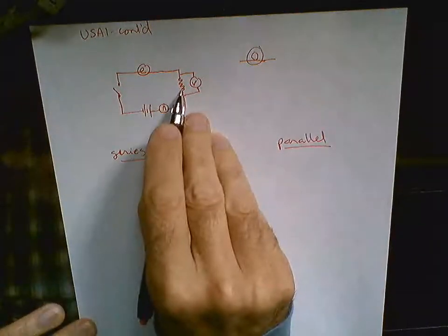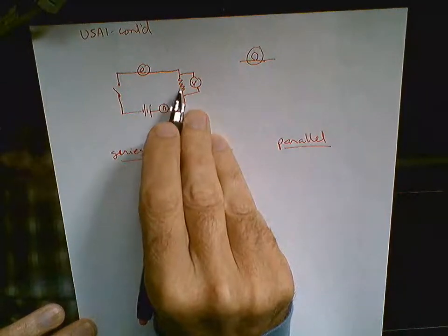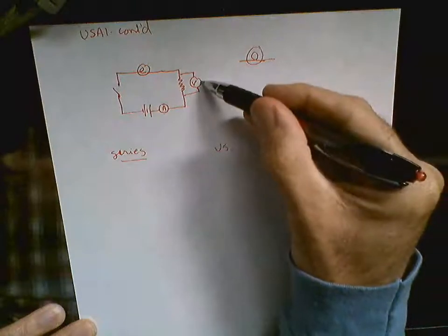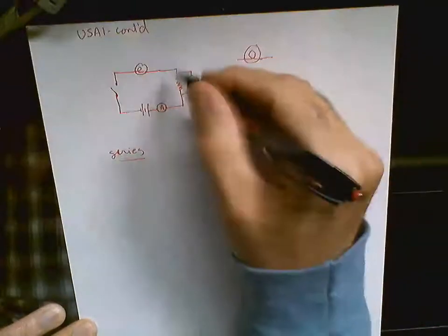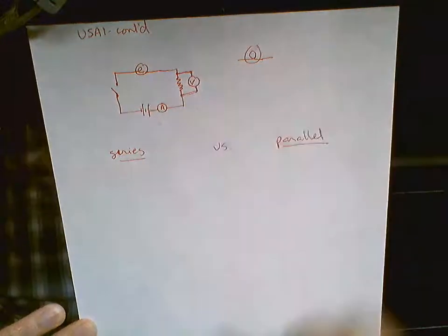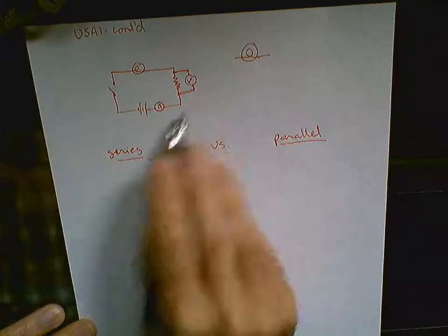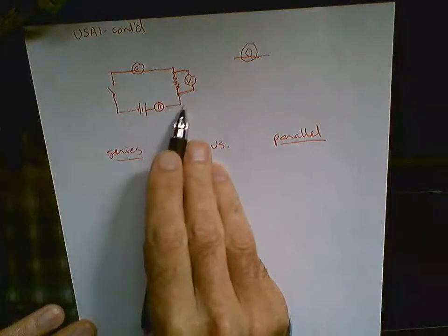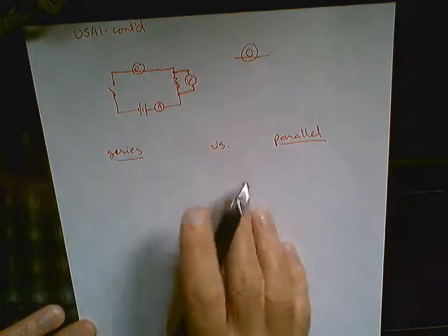This is what a resistor looks like. Sometimes we add resistors into systems to change the voltage. If you ever draw a voltmeter when you're in a circuit, it must go around a load of some type, so it must be in parallel. An ammeter measuring amps goes right in series within the circuit.